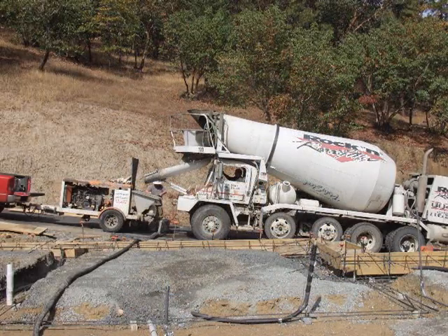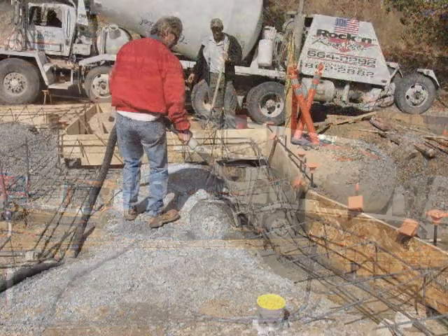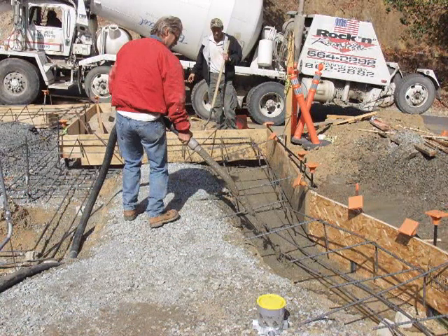And this way, with all of our bolts in place ahead of time, we can bring a concrete pumper in and use the hose to place the concrete in the footings while we can still walk around the rest of the slab. So here we can just use the hose to put the concrete exactly where we want it.